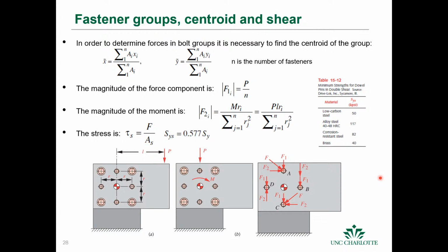When designing bolts, should we design them as dowels first and then decide the specifications for a bolt? No. So basically, if you're trying to keep two materials together, then it's just like all the other applications where you calculate the loads that you expect for that particular application, and you want to make sure that those loads don't exceed the loads that the bolts can handle or the loads that the material can handle.